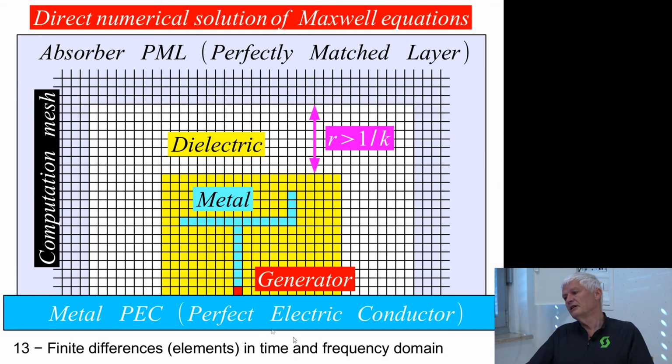What is the conclusion here? We have our antenna made from metal. This is metal. Maybe this metal may be enclosed in some dielectric, and dielectric may also have 3 dimensions. We cut all the space here in a cubic grid, or a square grid in 2 dimensions, a cubic grid in 3 dimensions, to calculate directly our equations. Of course, since we have such a stupid way of simulating things with a cubic grid, we need many, many, many more equations, many, many more variables.